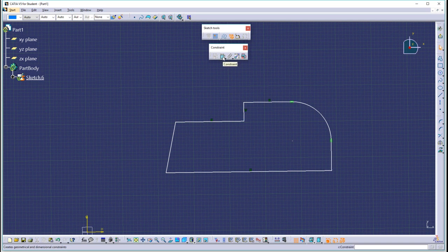Normally, I double-click this icon, and I just start dimensioning like this, just picking. So I can make a run on the entire part this way by picking all kinds of elements and just setting the dimensions. So that's one way to use this icon to create continuous dimensions.